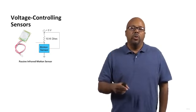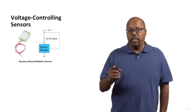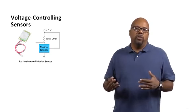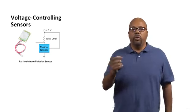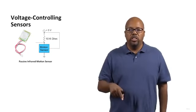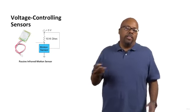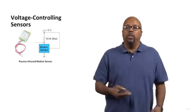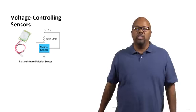Instead, they have a pin which outputs a certain voltage directly. And this is good for us because our Arduino directly senses voltage, right? So these voltage controlling sensors output voltage directly, and that's even easier for us. We can just take their voltage output and run it straight into one of the analog inputs of the Arduino and measure its voltage.